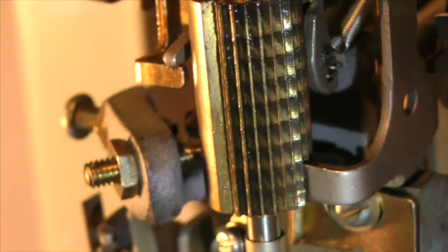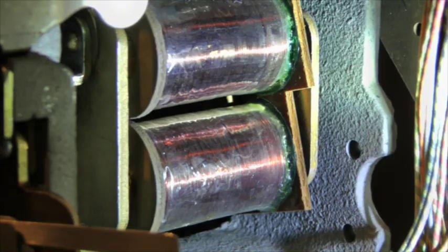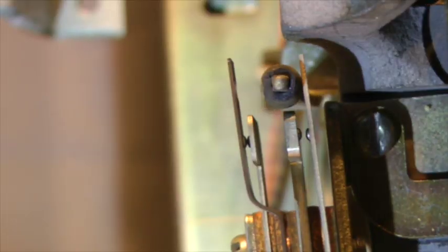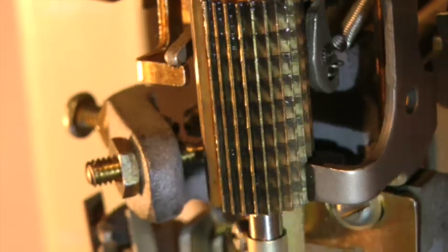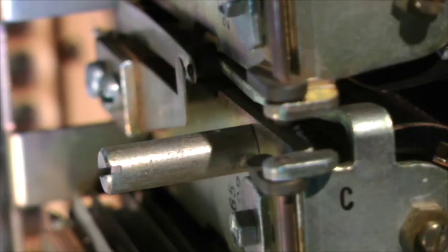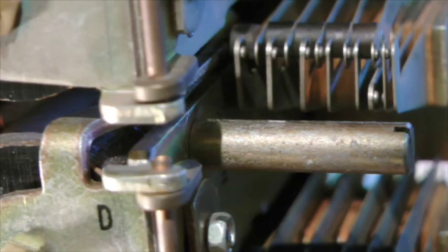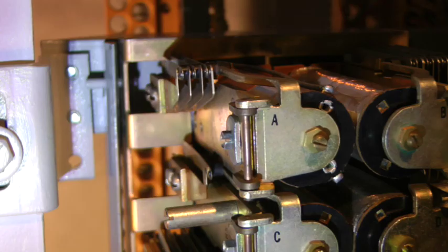The line finder is a non-numeric switch since none of its activity is in response to dial pulses. It functions somewhat in reverse to that of numeric switches, in that it is permanently connected to its succeeding circuit, which is a first selector, and takes action to connect to its preceding circuit, which is a calling line.